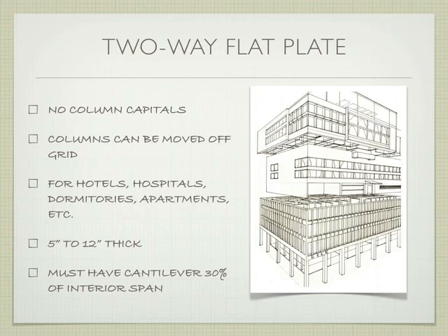If I have my floor, and I have my column happening here, and we have another column here, and over here we have another column here. If I end my slab here, I've got a bunch of weight pushing down here that's going to want to bend this column over on the outside edge. But if I put 30% out here, so that's 30% of this, there's a bunch of weight that happens out here as part of the floor that helps balance out the fact that it wants to curve in. Does that make sense? Just from a conceptual standpoint.